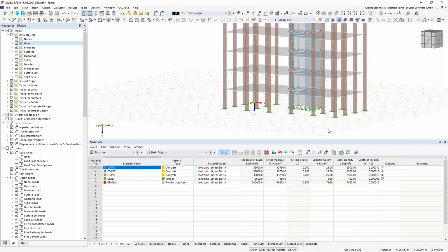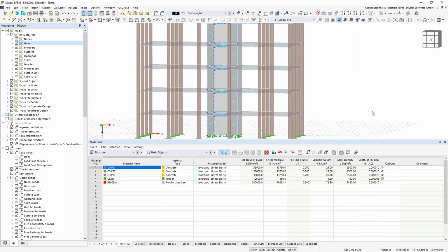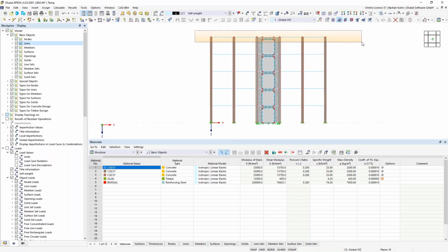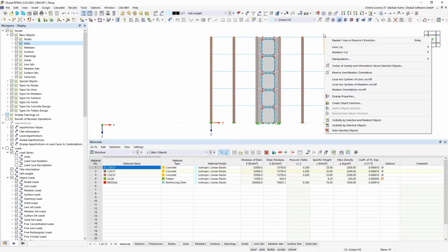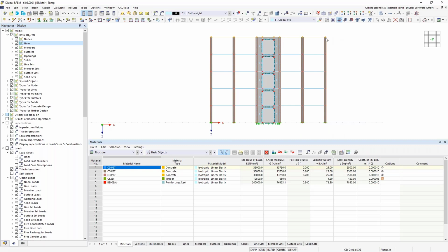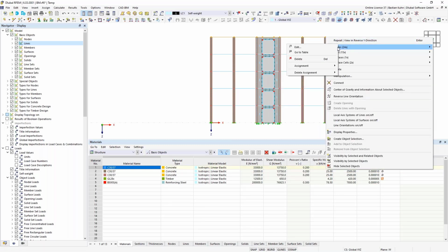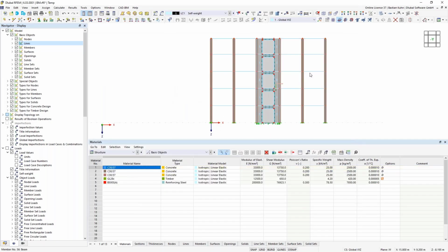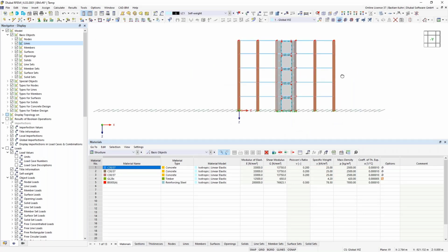And I want to show you that with this add-on, we are able to calculate also unsymmetric ground floor plans. So therefore, I'm defining the top story with a slightly different height. Let's say we want to be very economic, and therefore we just say the top 2 stories should have a height of 2.75 meter, which will be round about this, but minus makes more sense. So, all right. Okay, so yeah, it's quite narrow here, but it's still enough, I would say.